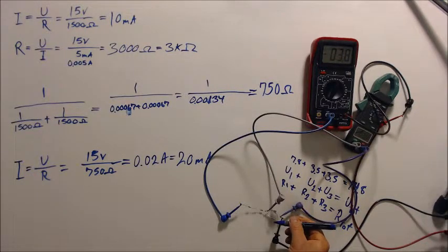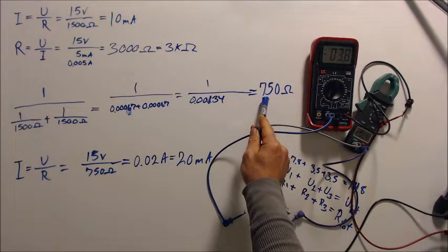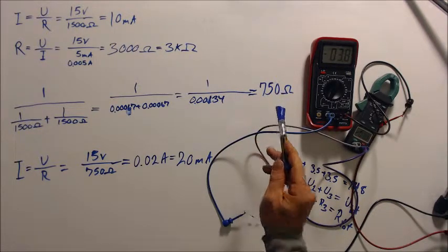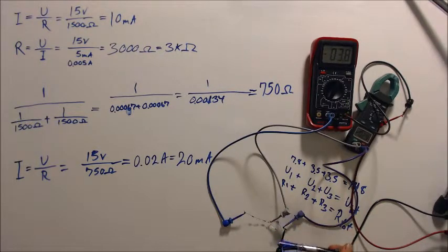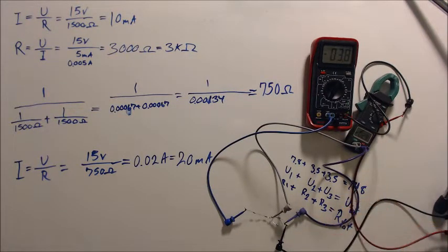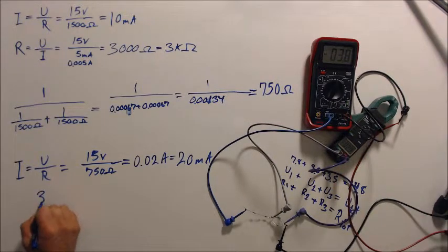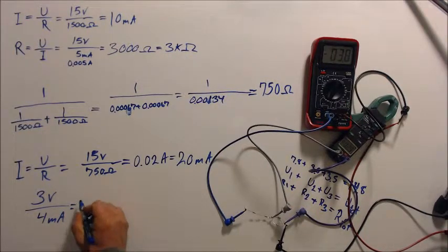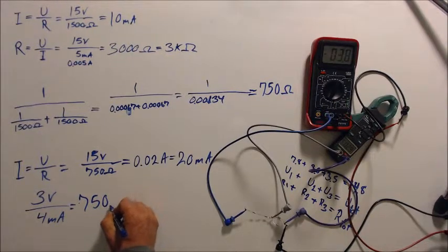So in this case, we have the same on both sides. And like you saw up here, that made the exact half of the resistance of 1. So we will have an even current load on both sides. Our voltage is not significantly high, but let's look at that. 3 volts divided by our... 4 milliamps, give or take here. We can now calculate in the opposite direction: 750 ohms. So it all makes sense.